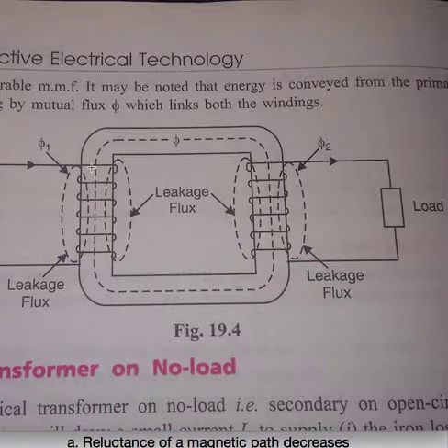In a distribution transformer, the primary side will be higher, about 11 kV, whereas on the consumer side, which is connected to the roadside or near the house, it will be about 230 V for a single phase transformer. So the number of turns in the primary will be more because the voltage is more. In order to get a lower voltage, the number of turns is reduced. So the answer is